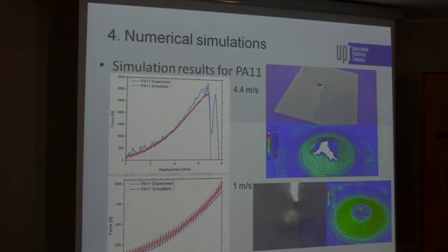Also, the fracture surface was similar, and in this case, we didn't have any puncture, but you can see this area here was damaged through crazing, the specific damage for polymers, and this was modeled as a set of elements removed from the bottom of the specimen, but no puncture was obtained.